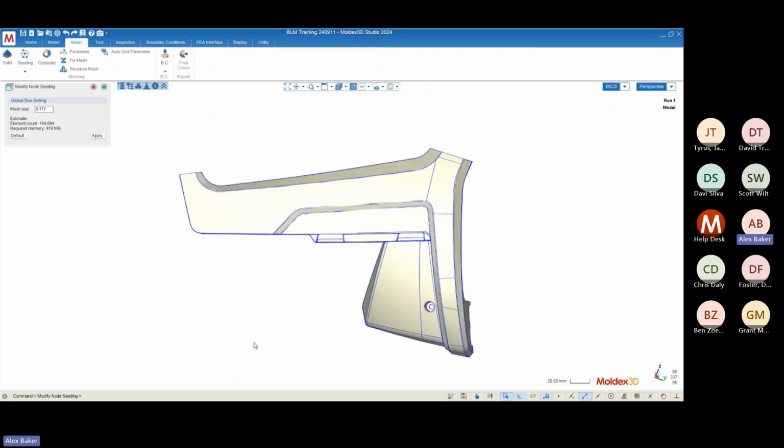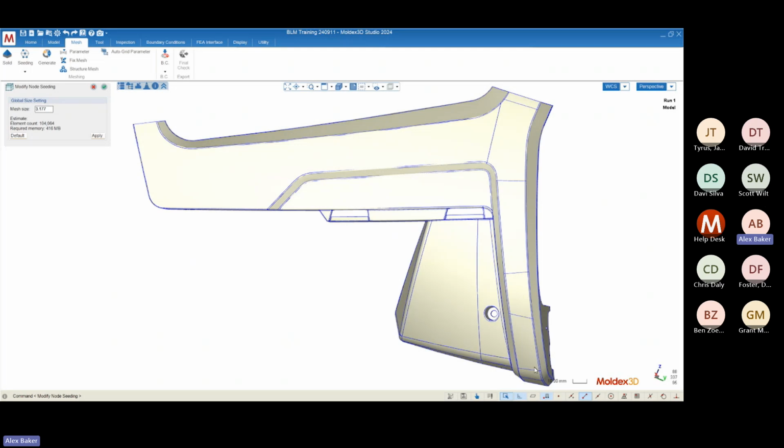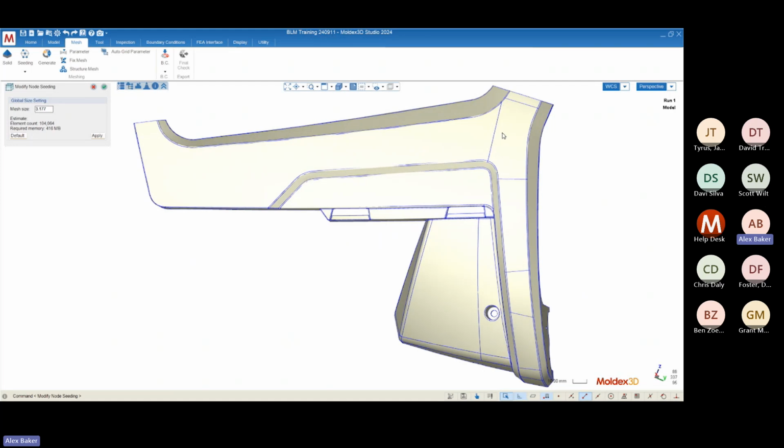And then I'm going to zoom in my geometry so that the part takes up the entire extent of the screen, either from top to bottom or from left to right, whichever one hits first. If I have a longer geometry, maybe the left to right dimension hits first, but generally speaking, I'll say maybe 80 to 90% of the time, the top to bottom dimension is what you're going to be looking for here.